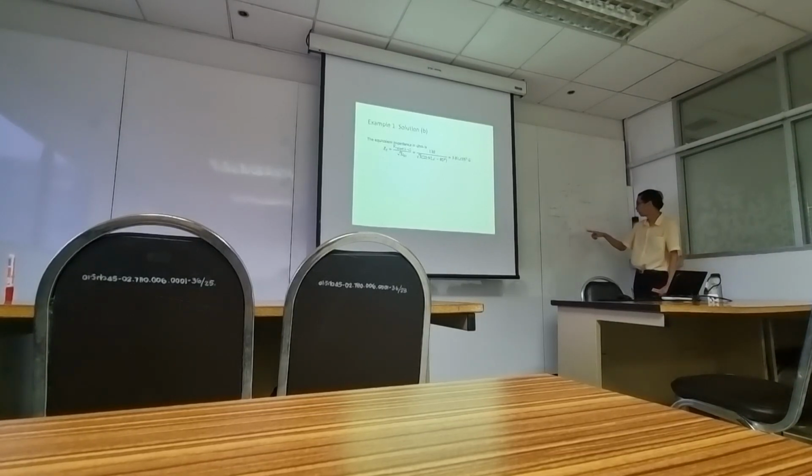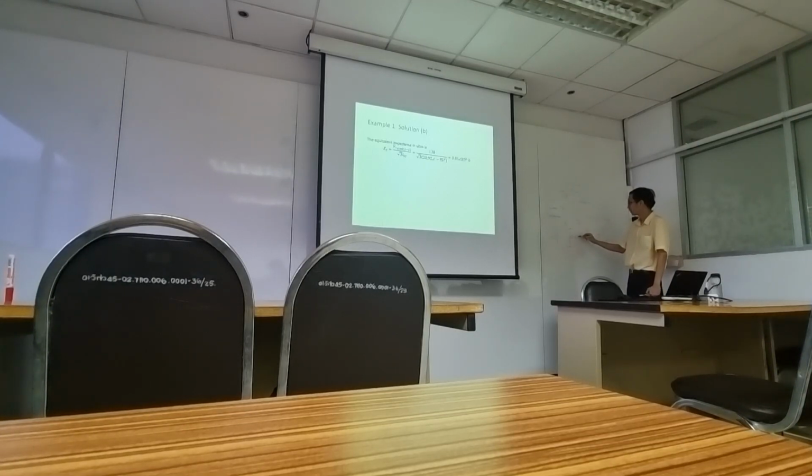Then, we have the short circuit current, so we want to calculate this impedance. It can be shown that the current is equal to VS rated line to neutral divided by ZS, right?